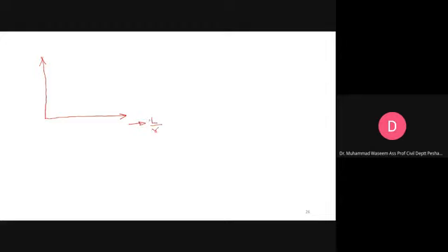If I add this k term here, it will not change. And on the y-axis we have the critical stress. If you remember, if you plot the original Euler formulation, is it convex or concave?